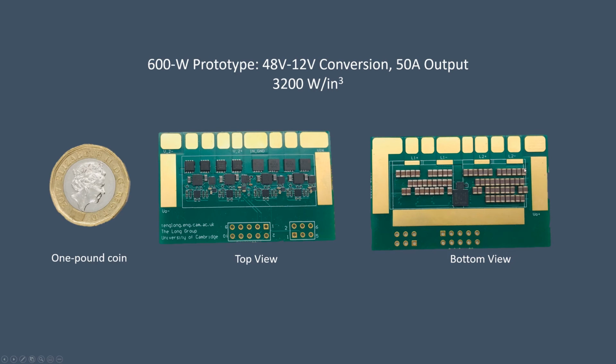All the capacitors are located at the bottom of the converter. All the auxiliary circuits are included in the SAC converter. We have 4 drivers to drive the 8 MOSFETs. We have the amplifiers to generate on-off signals for all the 4 MOSFETs. We have auxiliary power circuits to generate power for all the auxiliary chips. At the bottom side, we also have a CPLD as the controller to control the whole converter.